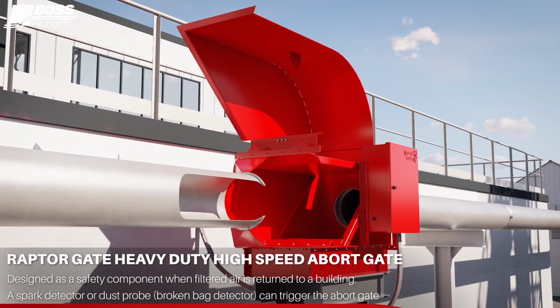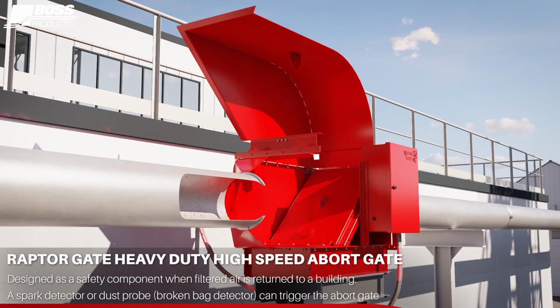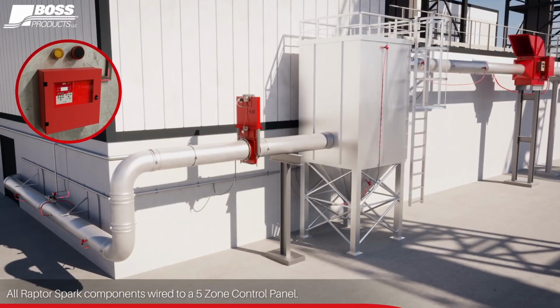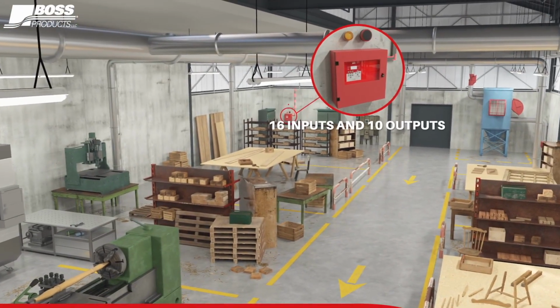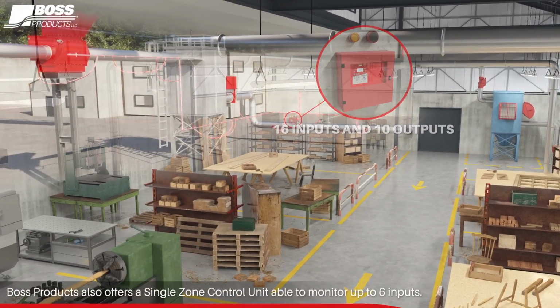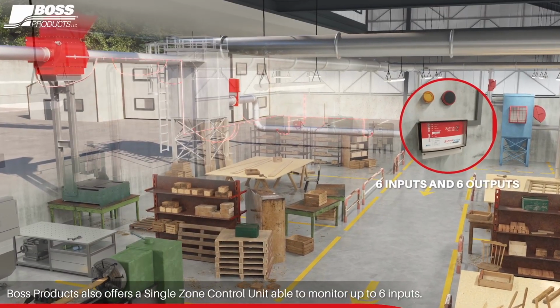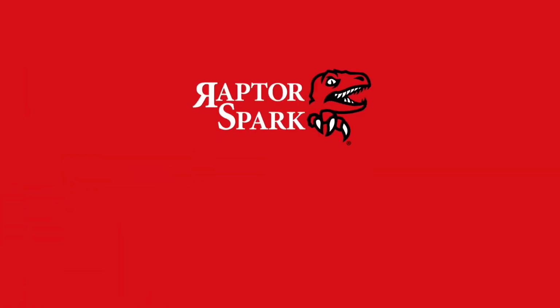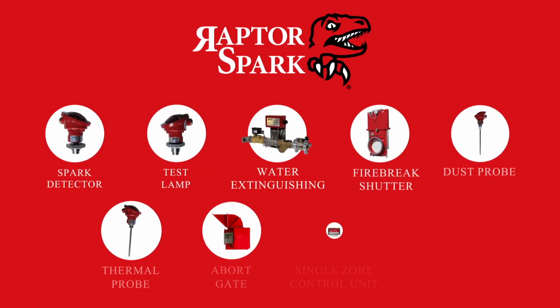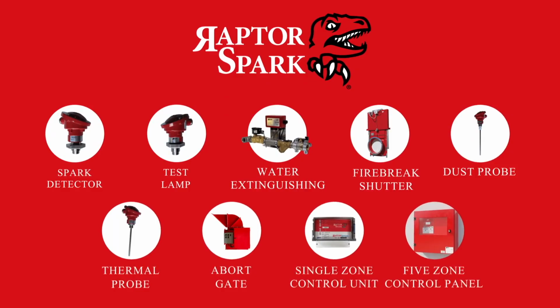And then I talked briefly about the abort gate, but that's what the abort gate looks like. It closes off the duct in the event of a triggering event, a spark, dust probe or thermal probe activation, and it closes off that ductwork. We can do different types of controls with this. We can offer different single zone controls up to a 5-zone control panel as well. So we can offer many different inputs, up to 16 different inputs and 10 outputs.